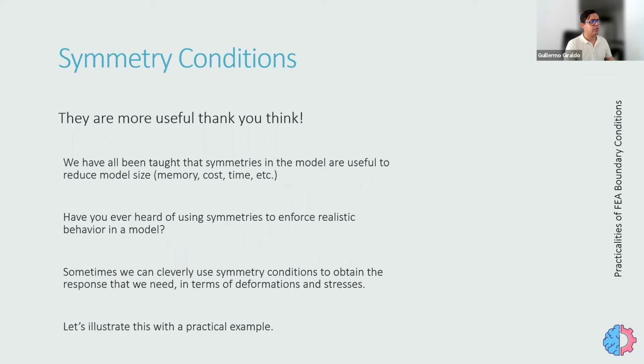But I want you to think that symmetry conditions sometimes can be more useful than that, and that sometimes we can leverage symmetry conditions to enforce a more realistic behavior in a model. What I mean is that our direct way of approaching modeling is, okay, I need to constrain the rigid body motion, so I will just throw some fixed supports here and here and here, so that I won't get any rigid body motion, and my model is properly constrained.